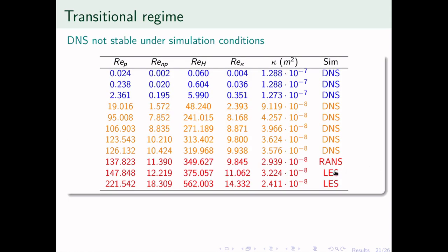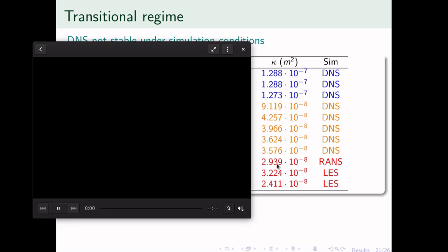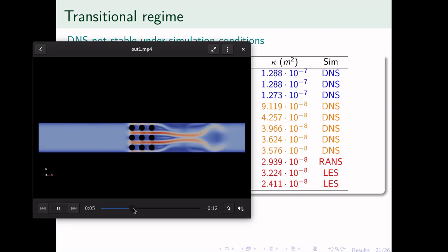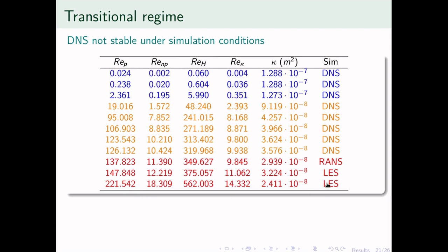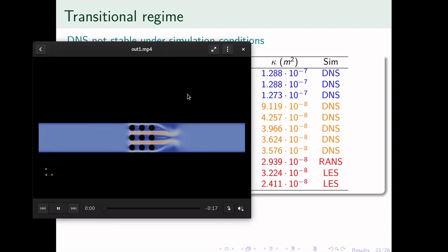And when we use the large eddy simulation, what you can see is that it captures the instability, which is more in line with what was seen before when we were using direct numerical simulation. You can see that as the velocity increases, the various forms of the Reynolds number increase. You can see the development in some instances even of turbulent behavior and fully developed instability here.